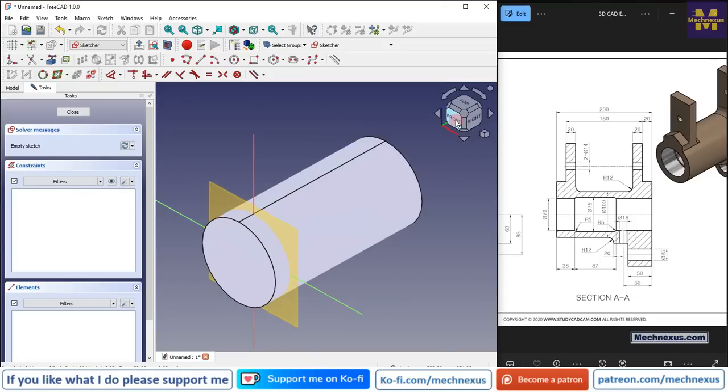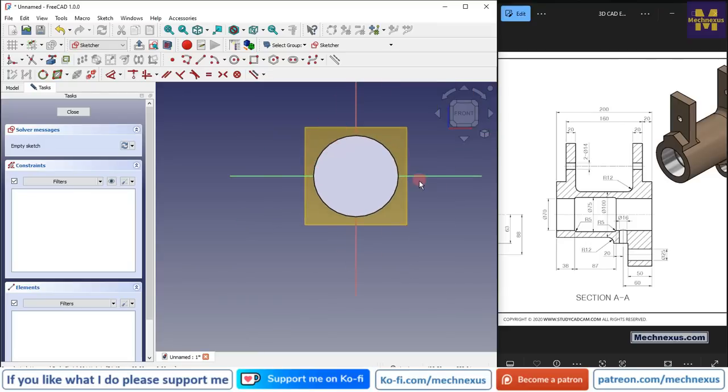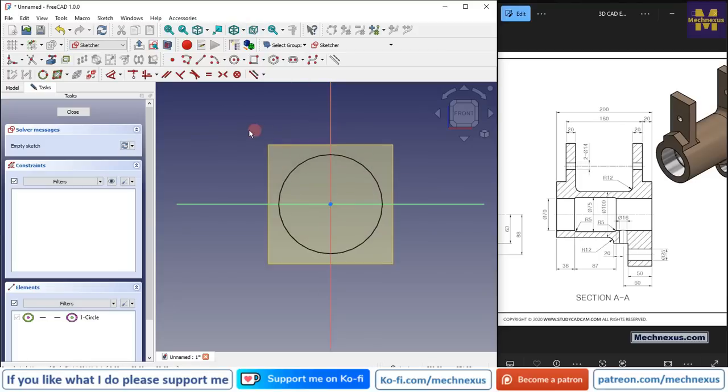So we will select this front, and now here we will project this diameter, and let's switch to the wireframe, and now we will select the 3-point arc.